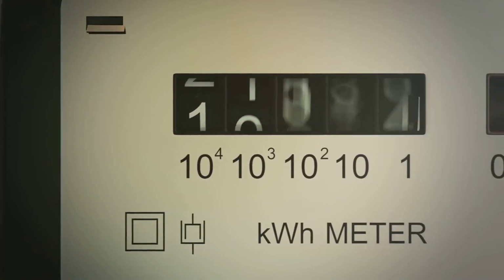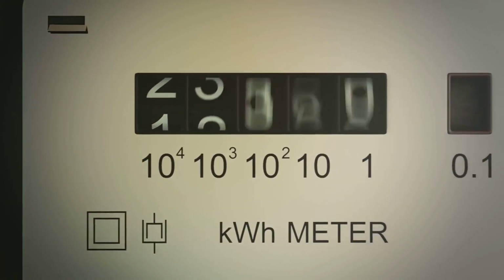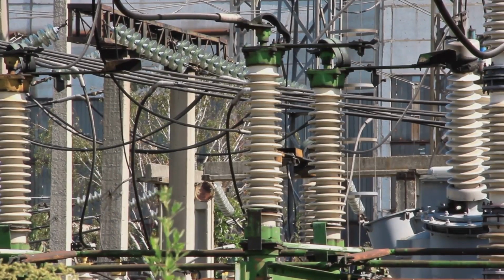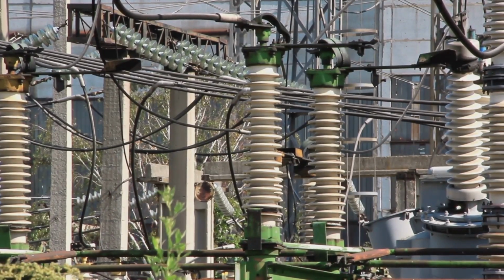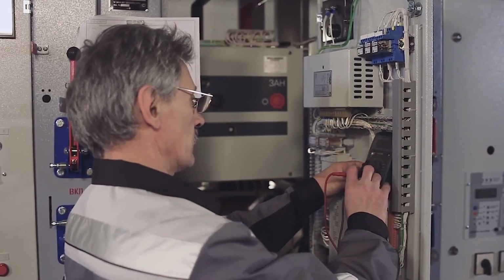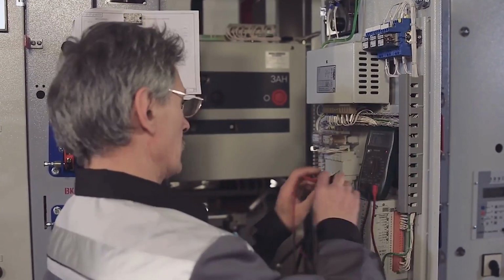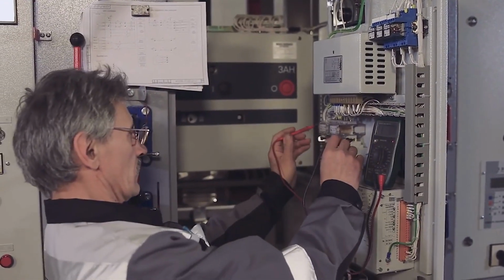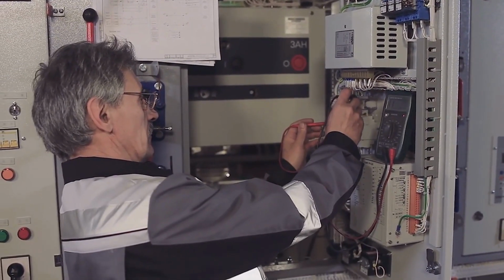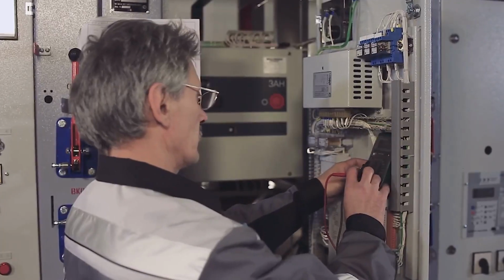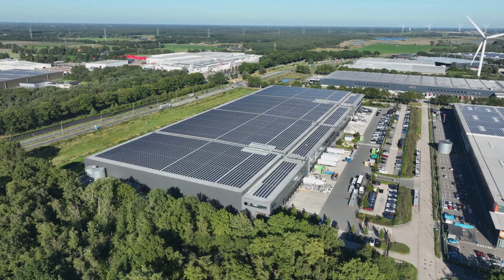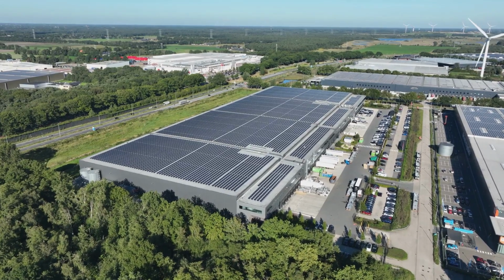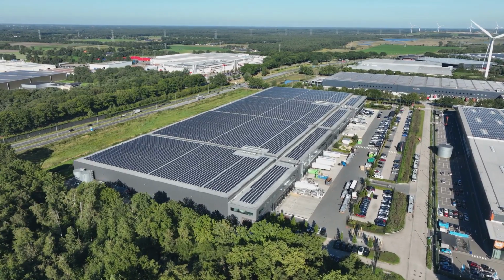Let's say you have a site with a power factor of 0.75. This power factor results in high apparent power demand and incurs reactive power charges from your electricity company. After installing a capacitor bank to correct the power factor to 0.95, your site reduces apparent power demand by as much as 20%, slashing energy bills and eliminating penalties. For a large-scale operation, that could mean savings in the tens or even hundreds of thousands of pounds per year.